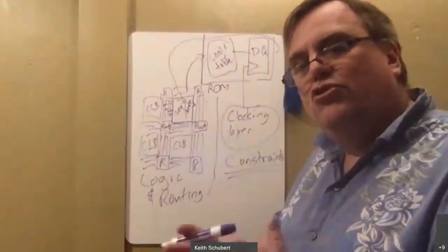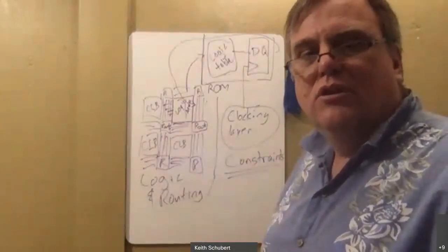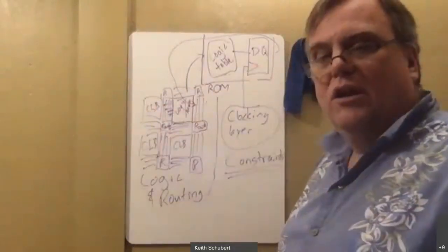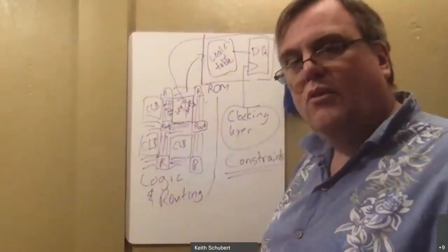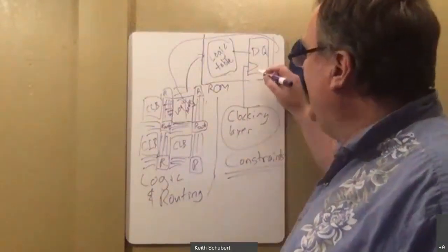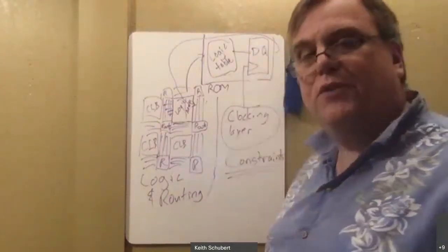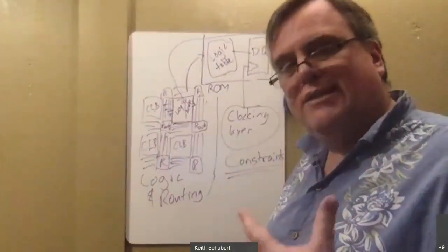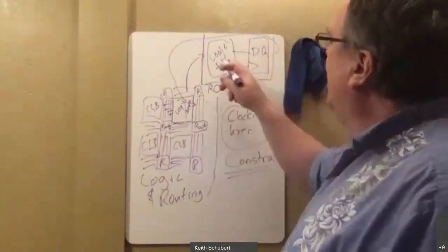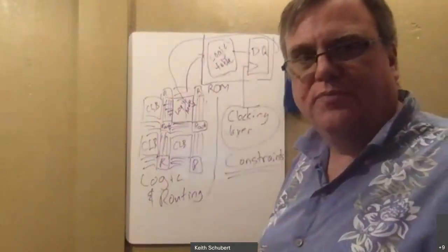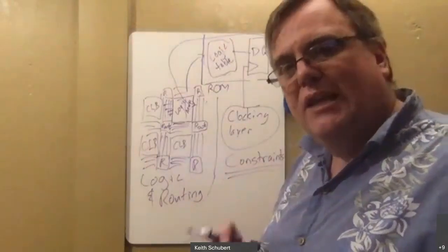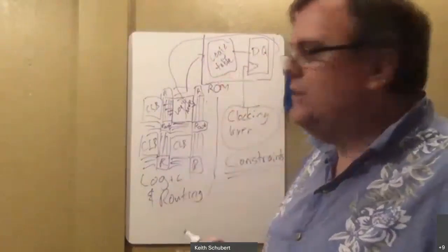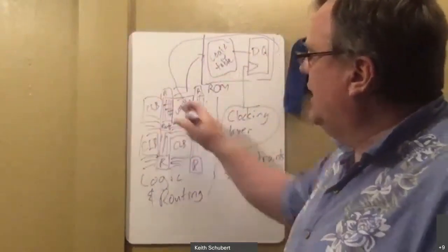But taking logic and putting it into here, FPGAs don't have a way to do that. So since it doesn't have a way to get this signal to here, but you told it to, what it has to do is fake it. Instead of using the actual D flip-flop that's built into the system and has good timing to it, it's going to attempt to build a flip-flop by feeding logic tables back into each other. The second it takes logic tables and feeds them back into each other, that's a really inefficient way to do it. So it's going to take a bunch of these logic blocks.